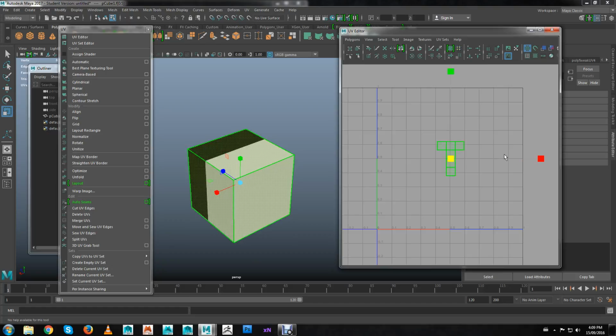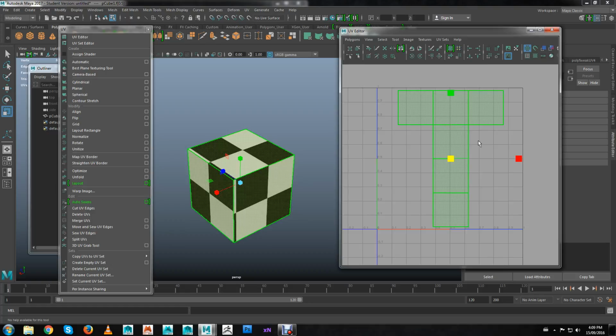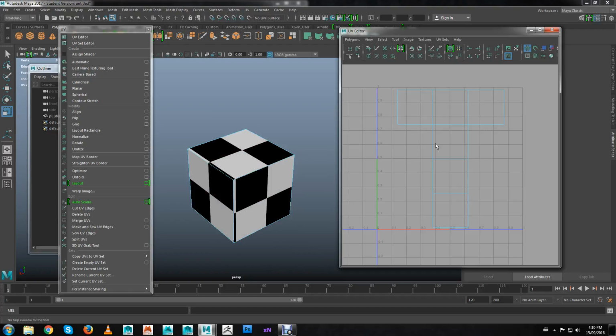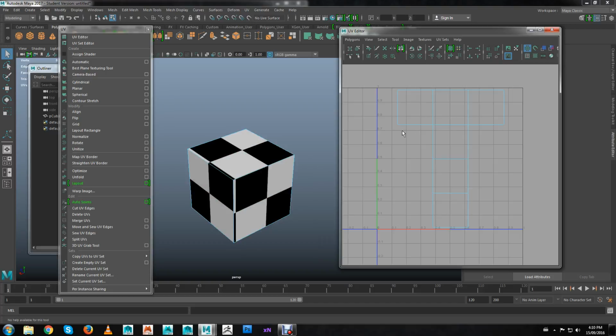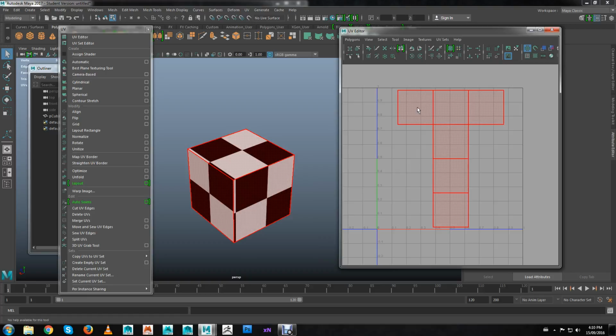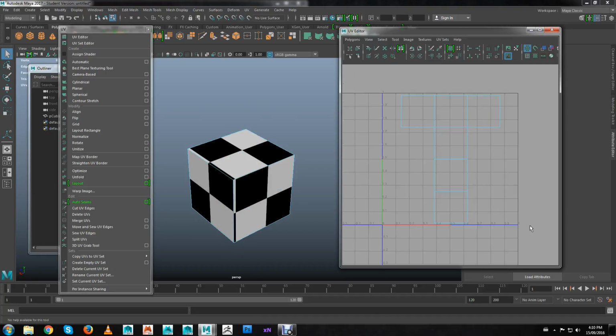Okay, so I want the UVs to be big. Okay, I want them to be quite large. All right, so I have this here. Okay, and I have now taken all of the UVs of my object and I've arranged them properly in this coordinate space. Okay, so I'm going to stop there. We've covered UVs, we've covered what shells are and how to make projections, simple projections, sew our shells together, and then arrange them in our upper right hand quadrant, a UV quadrant here.